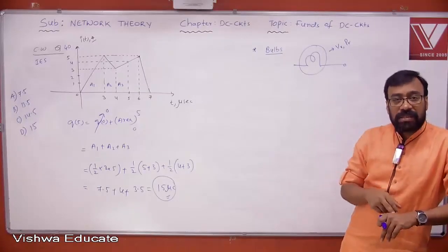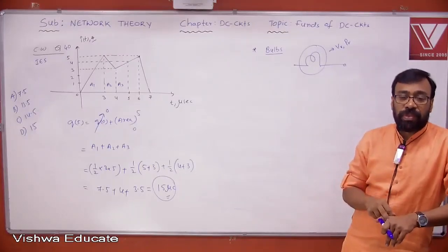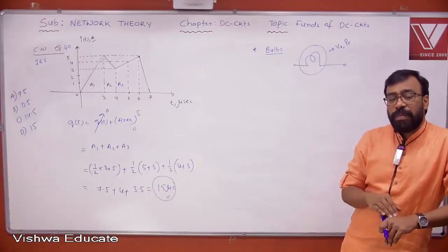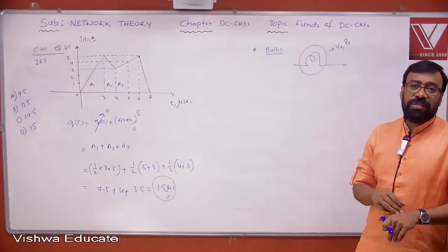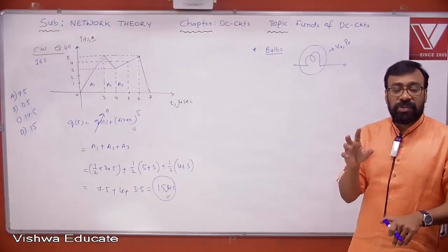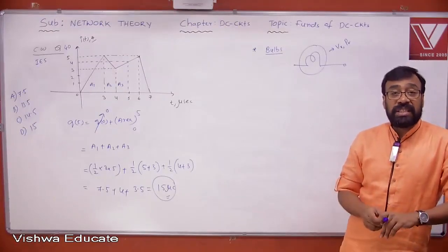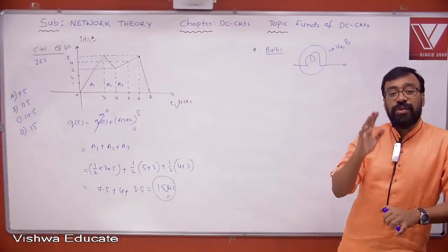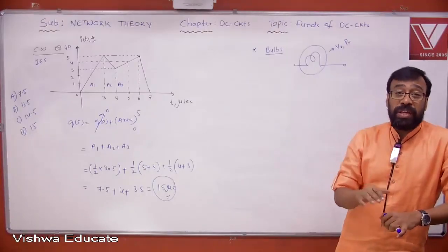But when you go to remote villages, people are definitely using tungsten filament bulbs only. What is the reason for that? The remote villages are still facing the problem of low voltage. Under low voltage conditions, the tube or the LED won't glow properly. They simply flicker. So this is a very important thing. In an interview, people may ask you where people are still using tungsten filament bulbs and why. In remote villages, this is the only bulb which glows even under low voltage condition.